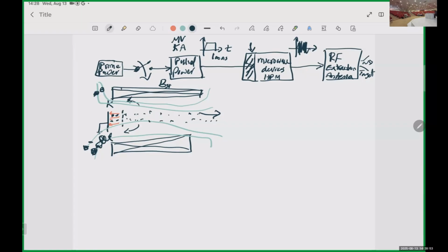If your electrons are in the parallel magnetic field, now you have a beam, you can use it for linear devices, PWT, backward wave oscillator. You can change the voltage between these two electrodes, and maybe I can write out here, cathode anode gap, and the voltage here may be 0 and this is 0, or maybe this is the anode at the ground and the cathode at the negative voltage.